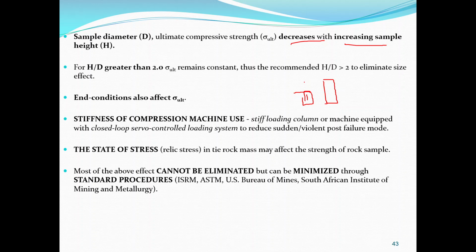If you have a larger size of diameter, sorry, we will not discuss that. We discuss height. If you have a height here and another height here, shorter and longer, then with the shorter height the ultimate compressive strength is higher, but the longer one has lower strength.